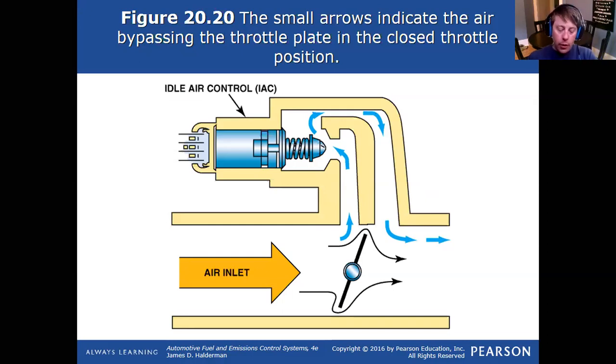So another example is you're trying to parallel park. So you're on the street trying to parallel park while you're turning your tires, and you're not rolling. You're actually causing a lot of drag, friction between the bottom of the tire and like the asphalt. And so the power steering pump has to be able to move those tires.